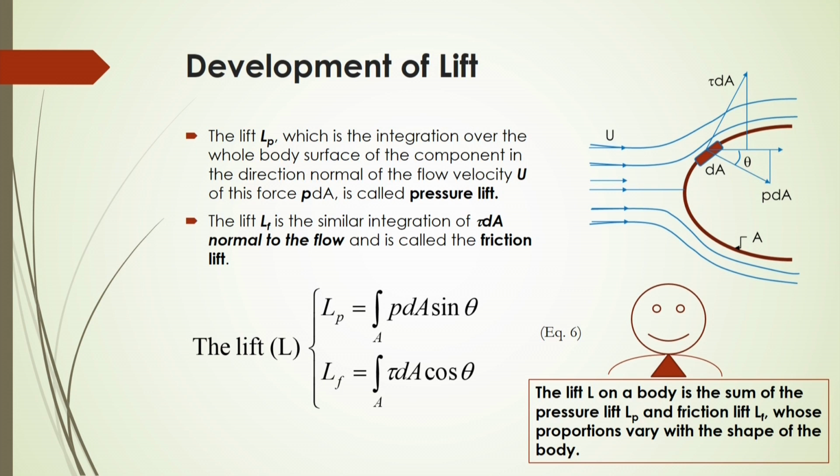Now, this lift, which is the integration over the whole body surface of the component in the direction that will be normal to the flow, we have already told in the previous or earlier slides. They are normal to the flow. If I consider this pressure force in the direction of the flow, this pressure force will be considered as drag, whereas if you consider this shear stress, you will see in this direction what would be the component, that will also be a component of drag.